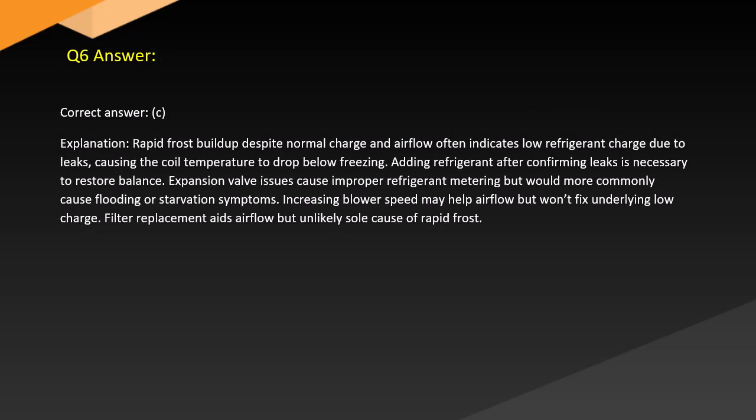Answer. Correct answer: C. Explanation. Rapid frost buildup despite normal charge and airflow often indicates low refrigerant charge due to leaks, causing the coil temperature to drop below freezing. Adding refrigerant after confirming leaks is necessary to restore balance.